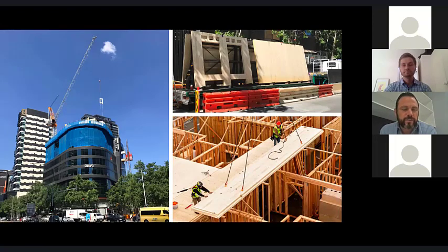But if there's any opportunity to get more than one crane on these sites, or supplementary cranes with a tower and mobile, you really need to start capitalising on that, because it is very crane intensive. The other image is a stick wall or prefab wall frame with CLT floors. And one thing to note here is that generally with the wall frames, you could lift the packs up onto the live deck and then stand them up manually, rather than having a crane picking up every panel individually or in groups like you can see at South Bank.